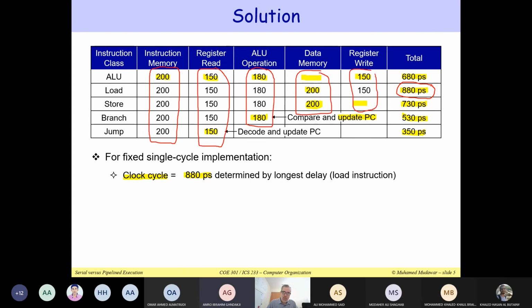Yes. So when you break down the steps of an instruction, in the case of the multi-cycle, we fetch in one cycle. We decode the instruction and read from the register file in another clock cycle. This is why I said that we have to have internal registers inside the CPU. These are different from the general purpose registers.